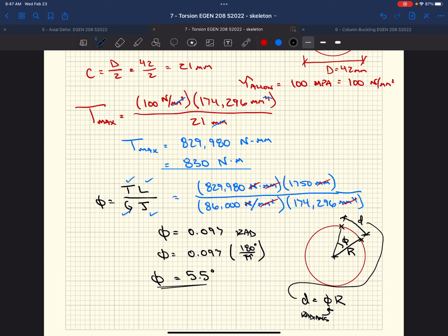That's where this plays into the real world of figuring out how we mate these two shafts and make sure the teeth are always in alignment based on the applied loads. One shaft might have an applied torque twisting in one direction, and the other might twist the other direction, to the point where the teeth don't line up, and then you no longer have nice mating of surfaces.